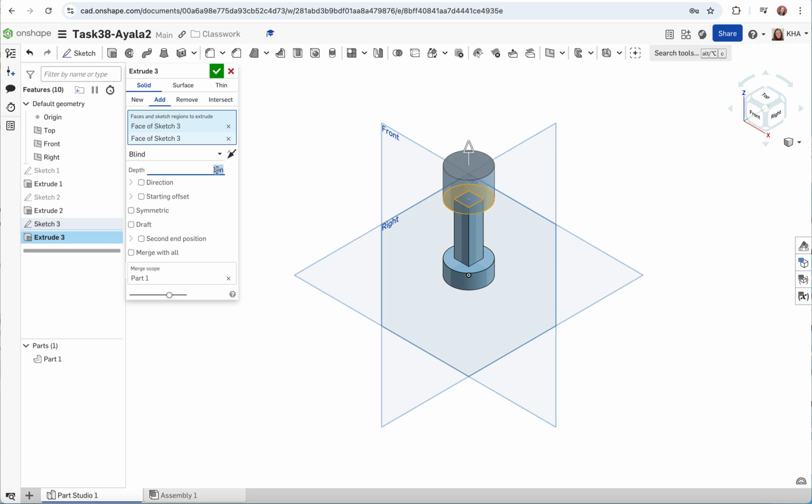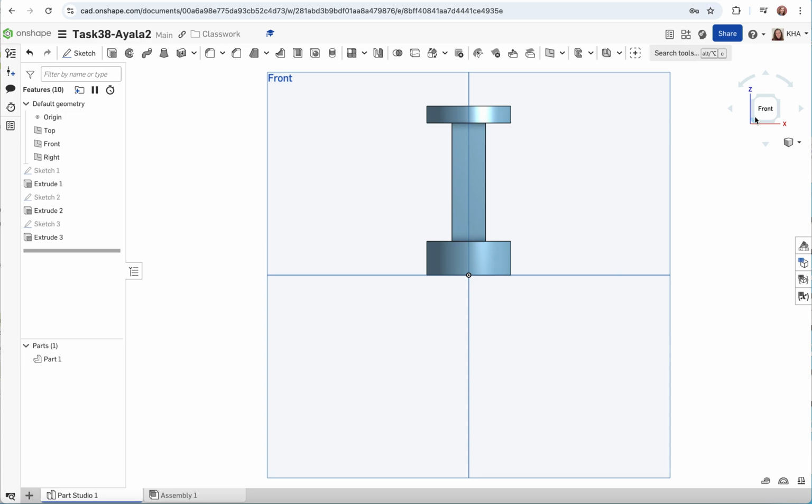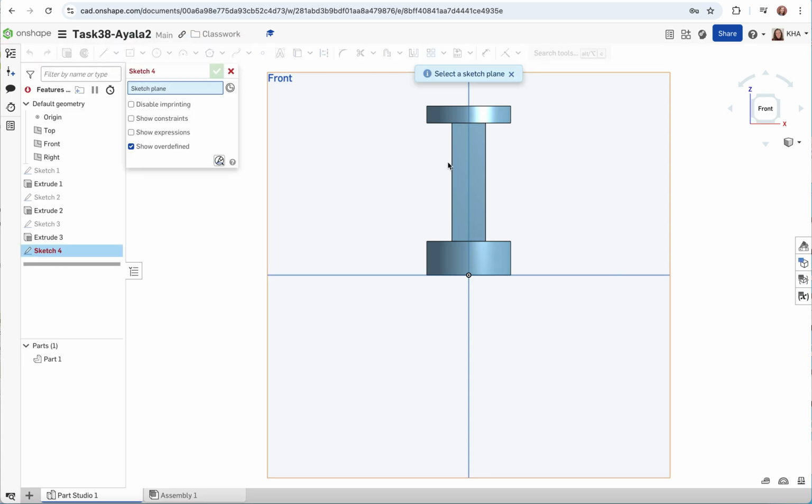We are going to set the height to 1/4 of an inch, or 0.25. And yeah, that's about right. We're going to accept the sketch. And we have made the broad strokes of this figure. What is coming next is some holes. So let's look right at the front of our figure. And we're going to make another sketch onto the front of this square pillar here.